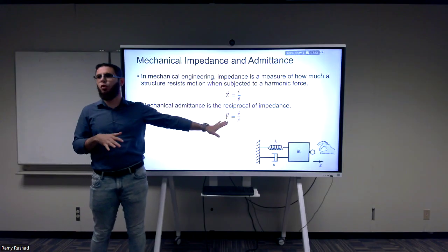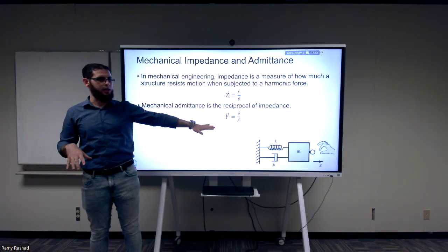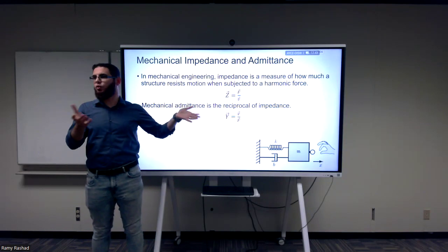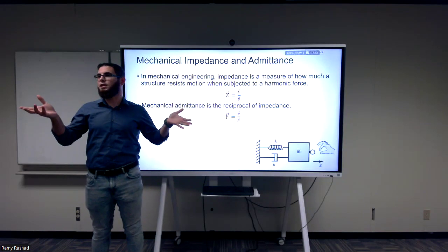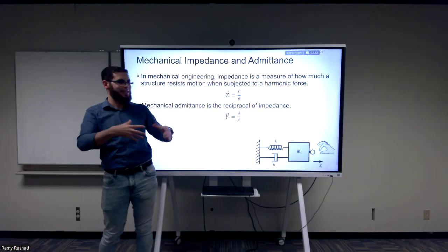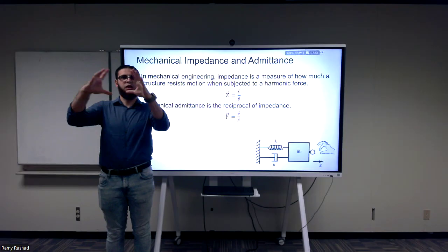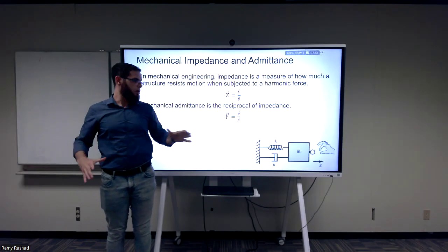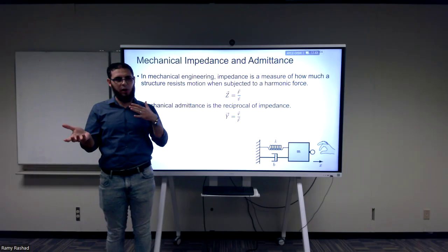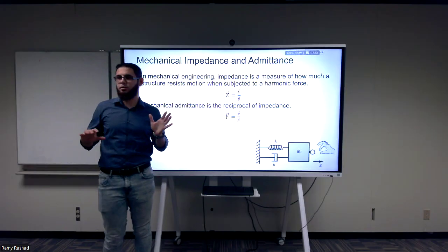And everything here works in 1D. So this is a 1D case, extends trivially to 3D. It also extends to 6D, but when we're talking about 6D, we're going to have a 6D spring, a 6D damper, and a 6D inertia. We know what the 6D inertia is. It's the generalized inertia tensor. But what is the 6D spring and what's the 6D damper, for next time, inshallah.